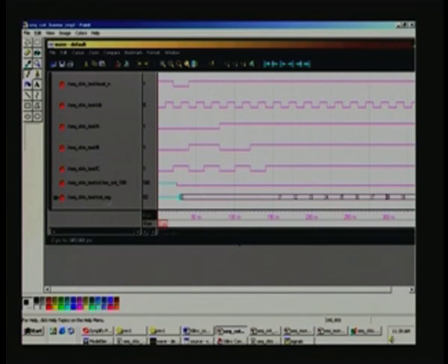You can see here a counter being reset to 0 corresponding to a reset pin here, and you note that reset happens right here, whereas only after a delay this 0 has been reset. Earlier it was not the case. Probably in the optimization phase, we did not get any delay as such. There was a delay somewhere else, maybe after the counter started.